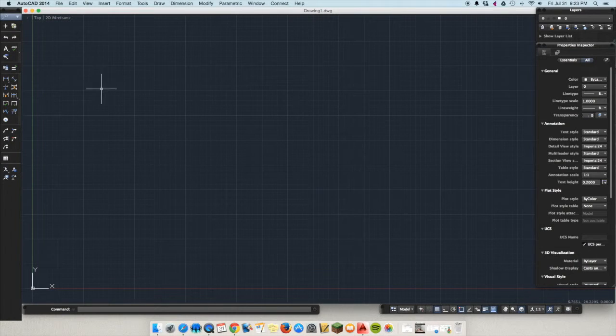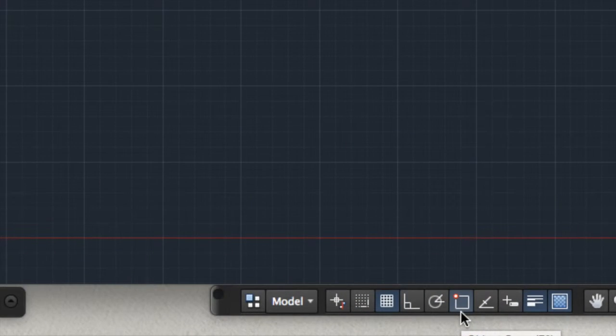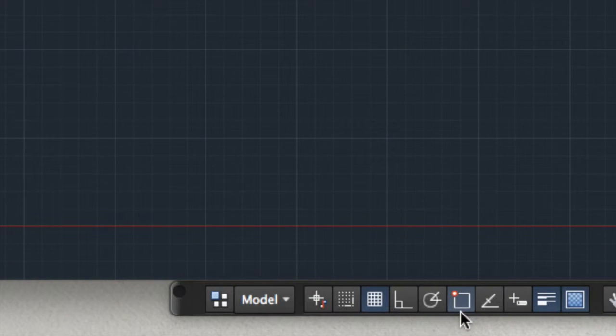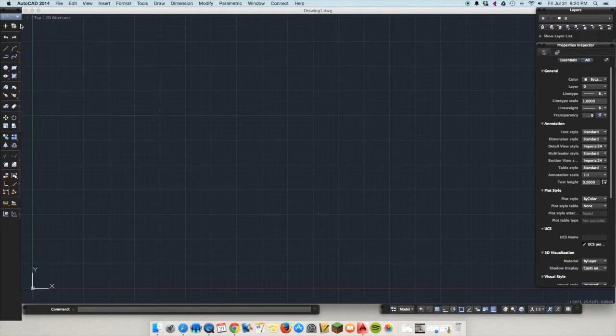Okay, so now we're going to try to make the spiraling square. To get started in here, let's check. We're going to use our relative coordinates to make this happen. I just want to check and see if there's anything on the status bar that we need to change, and I don't think there is. If your status bar looks like this one here, with the grid turned on and the object snap turned on, then you should be all set. So make sure you're in the drafting tool set. I'm going to go to line, and we're going to start this drawing at 1, 1, because remember you can't have a relative coordinate without having a starting point. So we're going to start at 1, 1 and hit enter.